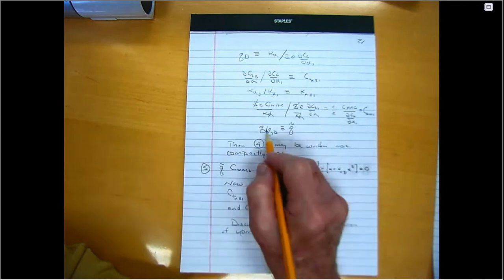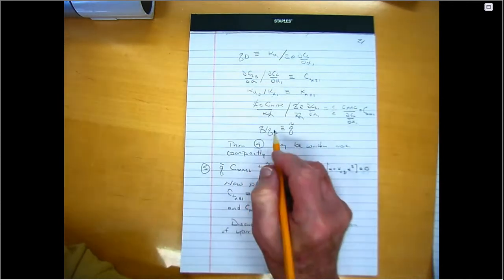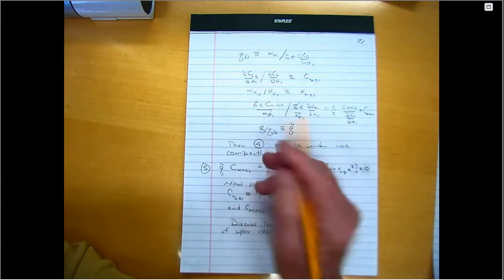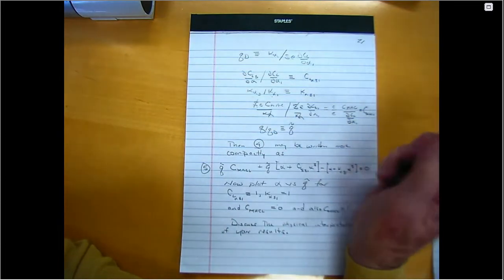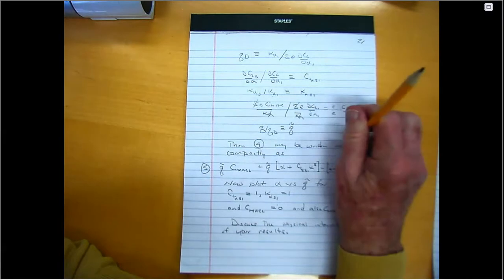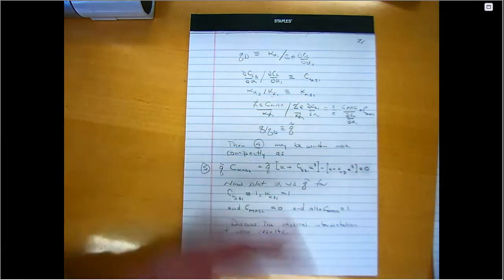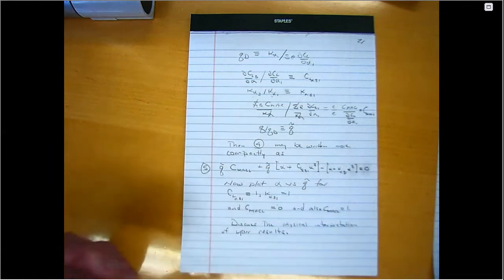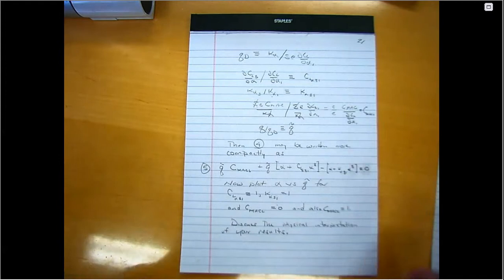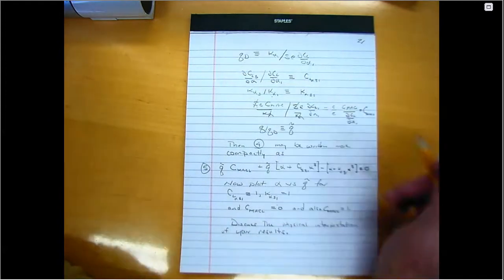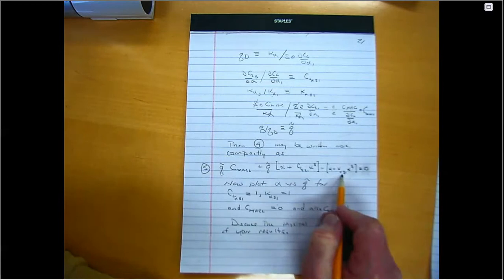And then I'm going to non-dimensionalize Q by QD. I can non-dimensionalize some other way. Non-dimensionalize the dynamic pressure by the divergence dynamic pressure. The linear divergence dynamic pressure is a useful thing to do, right? Because when it's 1, I expect to see something interesting. If it's less than 1, one behavior occurs; if it's greater than 1, some other behavior occurs. So using all of these non-dimensional parameters in a compact way, here's my equation again.